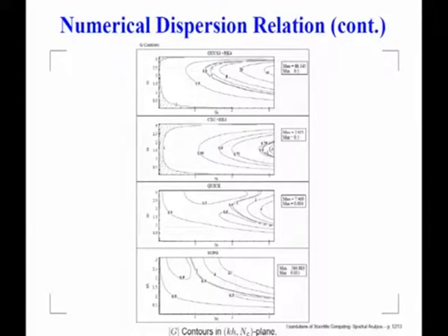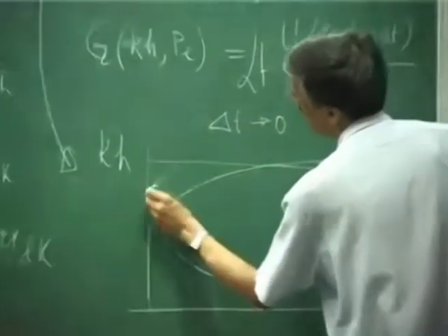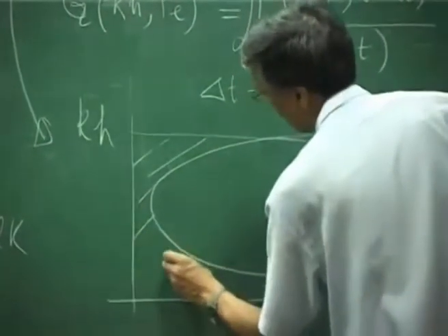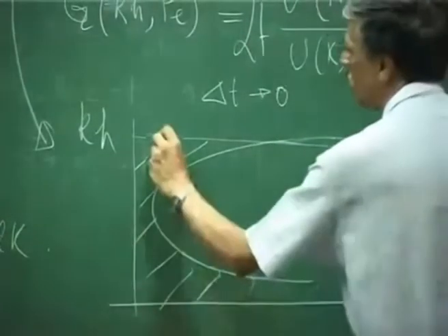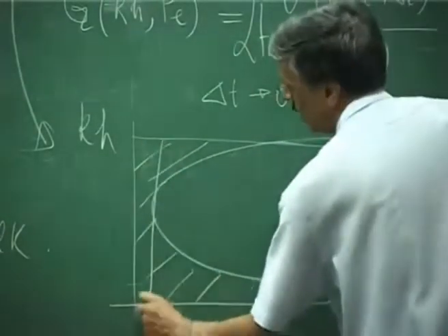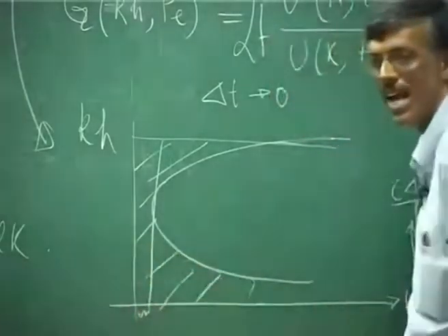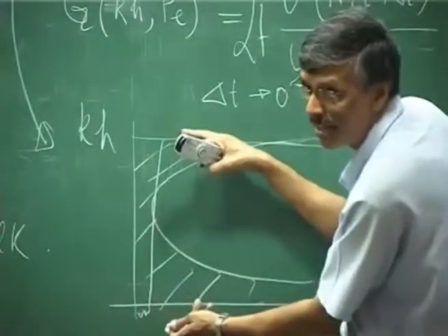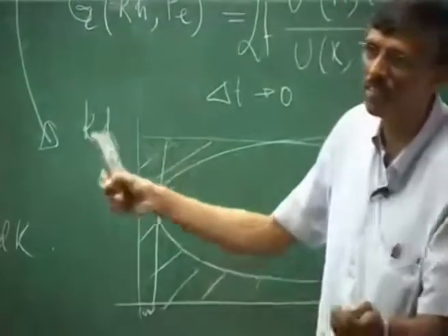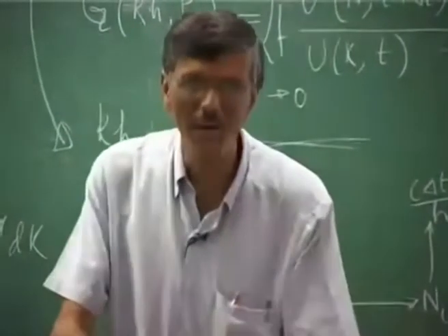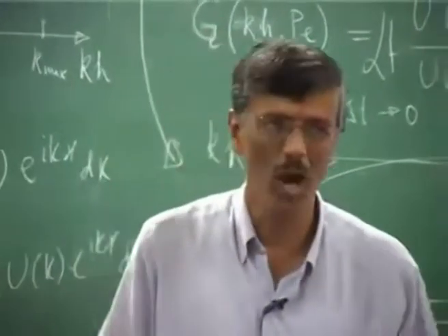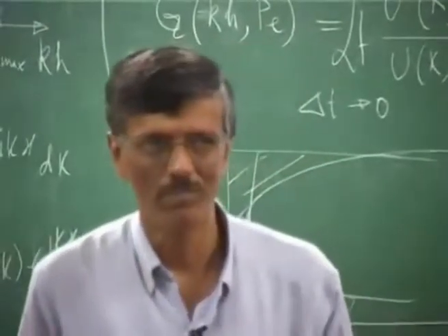So, after you have done that, this is the story that you would like to get from those G contours. So, let us say this is your region where you can confine yourself. I would say this is my usable NC range, for which whatever K max we have chosen, everything is resolved without any numerical attenuation. So, now you see this is the third step.